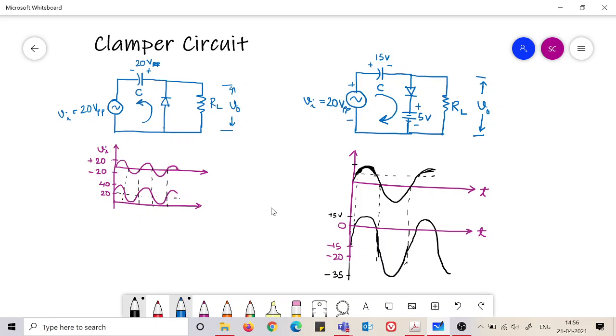So be careful, look at the circuit, understand what is there in the circuit. Is it only diode and resistances? Is there a capacitor? So this thing you first identify, then you slowly progress, try to understand in which region of the input voltage the diode would be forward biased, in which it is reverse biased, and when it is forward biased, some type of output.